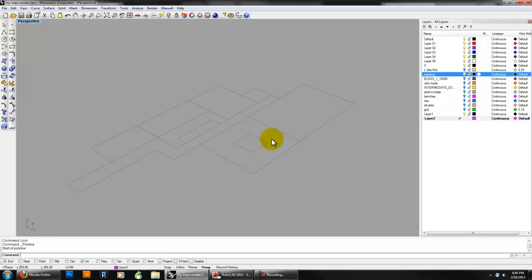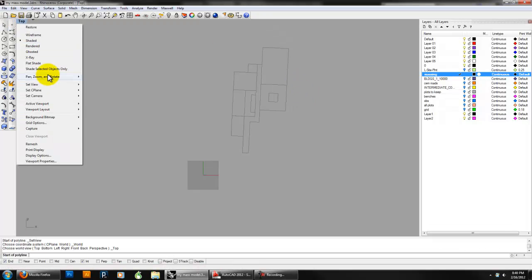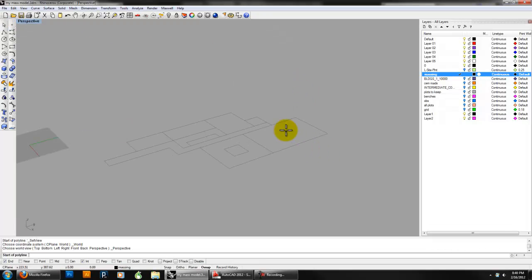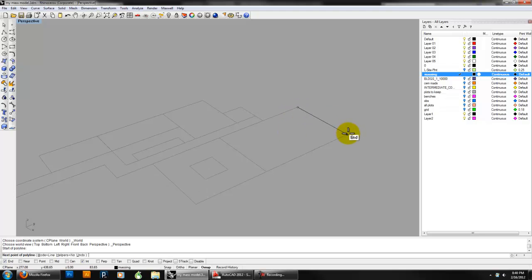So I'm going to start with my chapel and make a box, and I'm going to snap to... actually, I need to change my layers. Let's say set current to massing. Take my box. And using endpoint snaps, I'm going to snap to my chapel. Ooh, actually, I need to make a polyline instead, because it's actually angled. If I go to the top, you can see it's slightly angled. So, polyline it is. So, I'm going to draw.